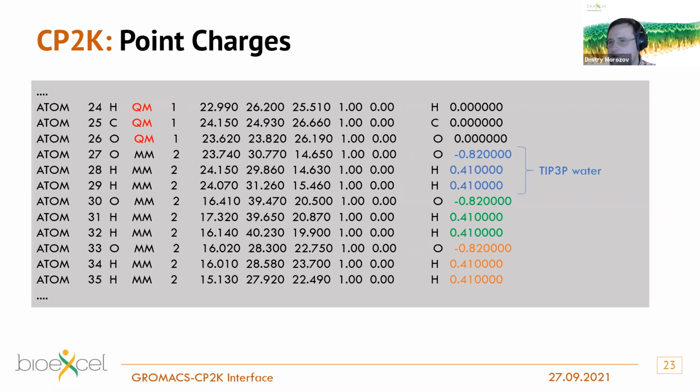Why do we need to do that? Because we also want, of course, CP2K to know partial charges of all MM atoms here. And for that, we are using an external PDB file with the so-called extended beta field that contains the point charge. The extended beta field is the one in the PDB file which starts at column 81, I guess, or something like that. It should usually contain beta factors, but in our case, it contains charges.